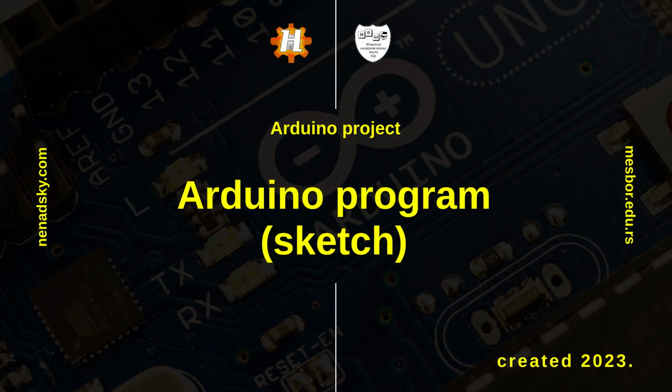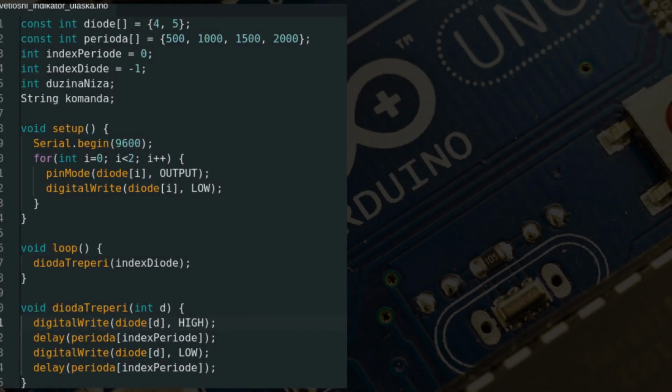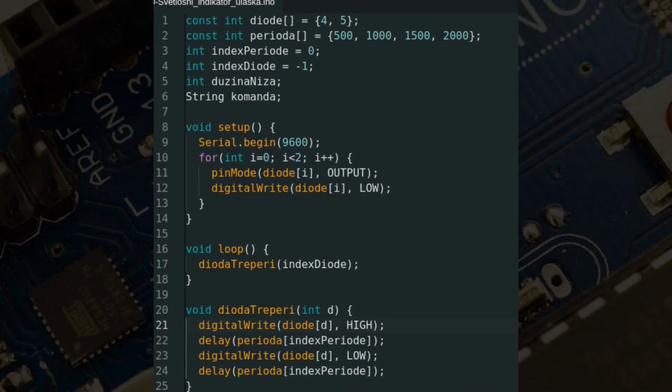Arduino program, Sketch. The LEDs are connected to digital pins 4 and 5, which is defined in the program by an array, LEDs, whose values are 4 and 5. The period during which the LEDs blink is also defined by a period array with the values 500, 1000, 1500 and 2000. These values represent the time interval that the LEDs are on and off expressed in milliseconds.